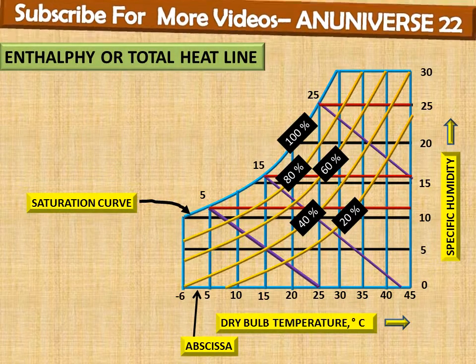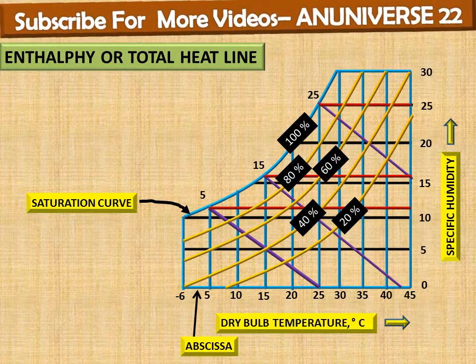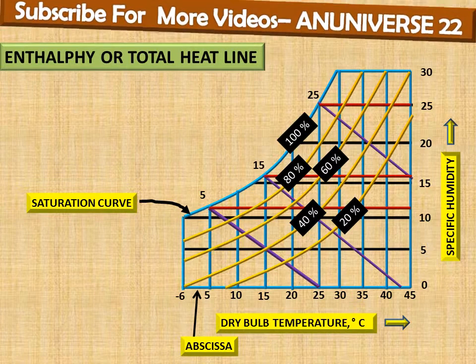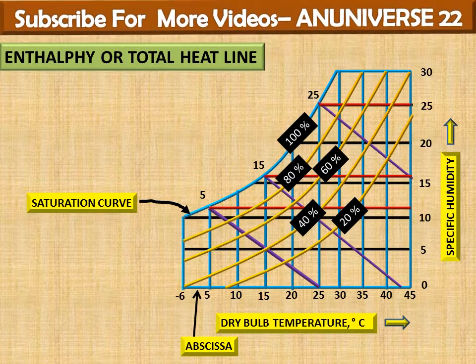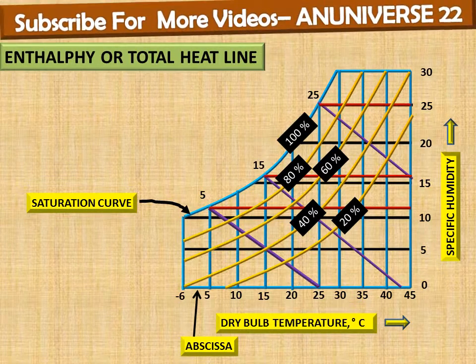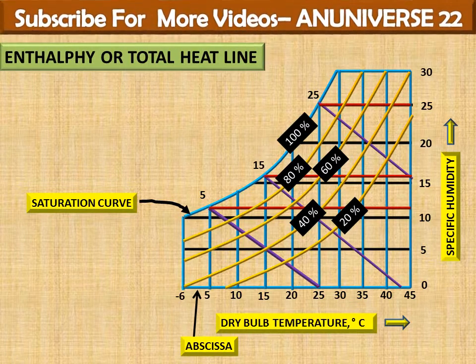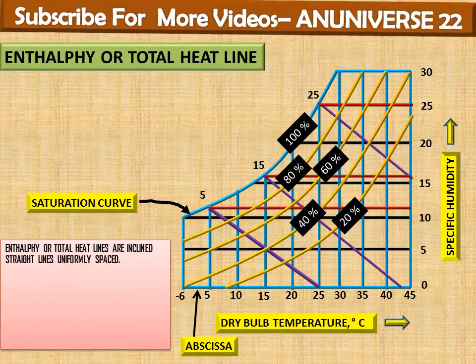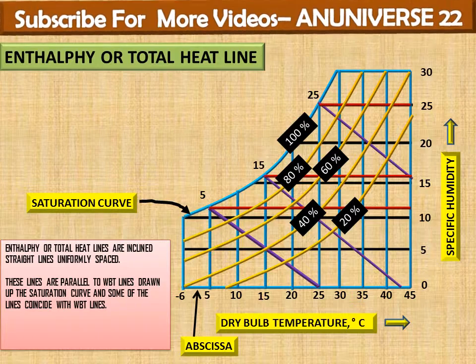Next line is the enthalpy or total heat line. The enthalpy or total heat lines are inclined straight lines, uniformly spaced, and these lines are parallel to the wet bulb temperature lines and drawn up to the saturation curve. So as we can see, heat lines are inclined straight lines, uniformly spaced and parallel to WBT lines, and go up to the saturation curve.